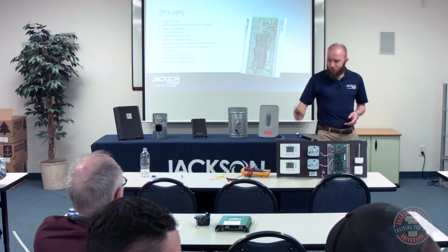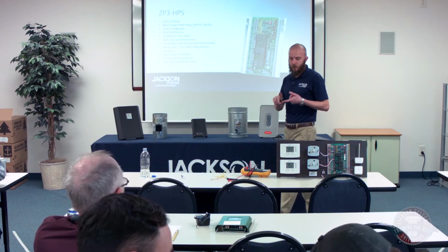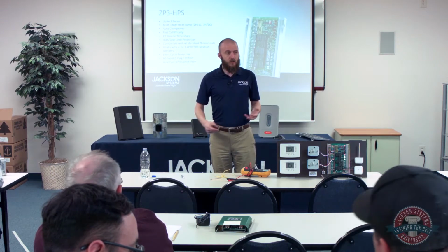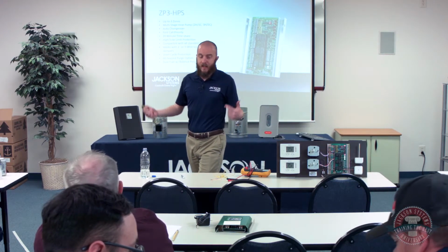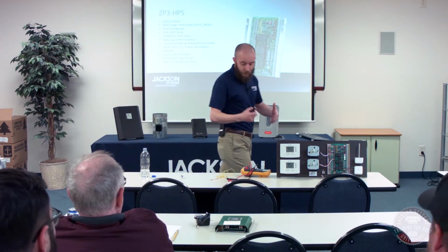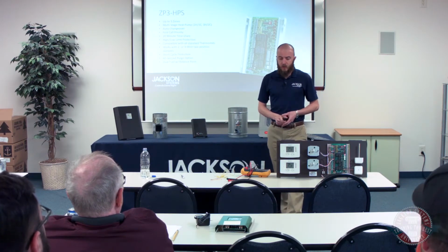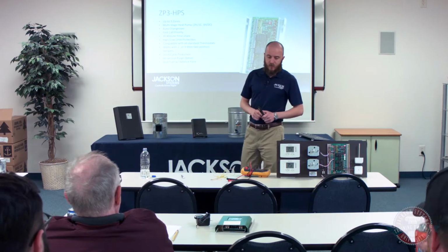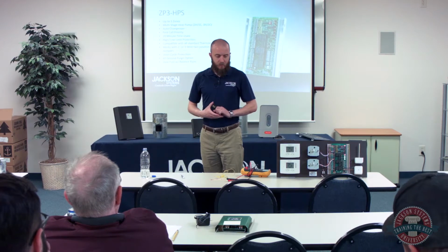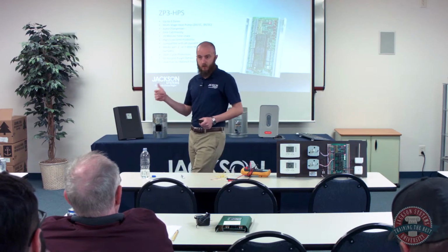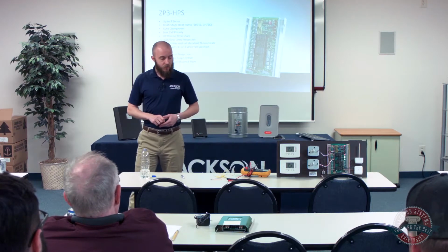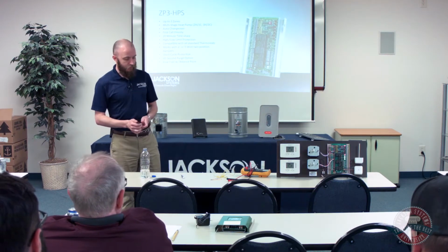So, for example, this board will do up to 3 zones. It'll do multi-stage. It has auto changeover, so if it receives heat calls and cool calls, or heat calls from one zone, cooling from another, it can interpret those and knows what to do with those. Compatible with all your standard thermostats, works with 2 or 3-wire, 2-position dampers, has short cycle protection built in, so there's some time delays. Has a 60-second purge option, and also has dual fuel control options.